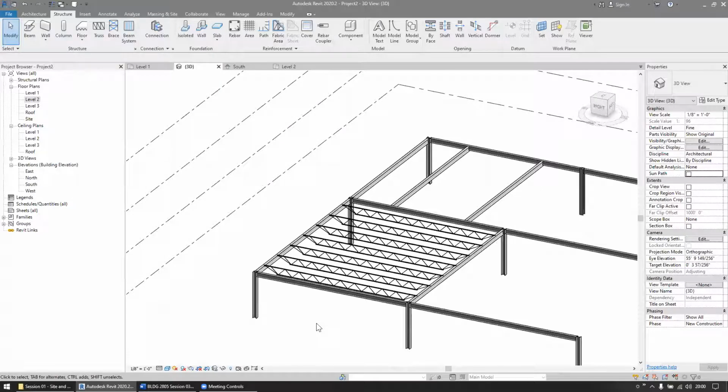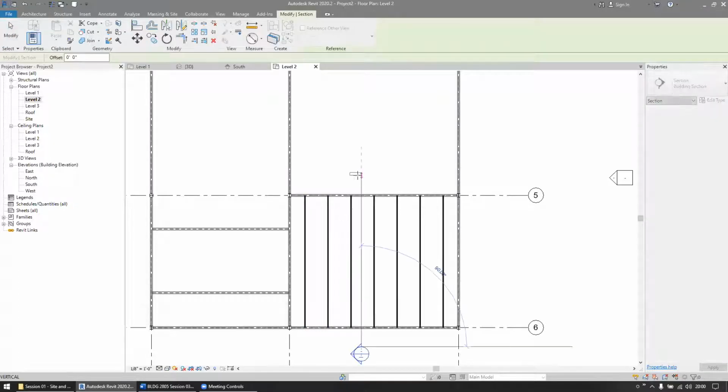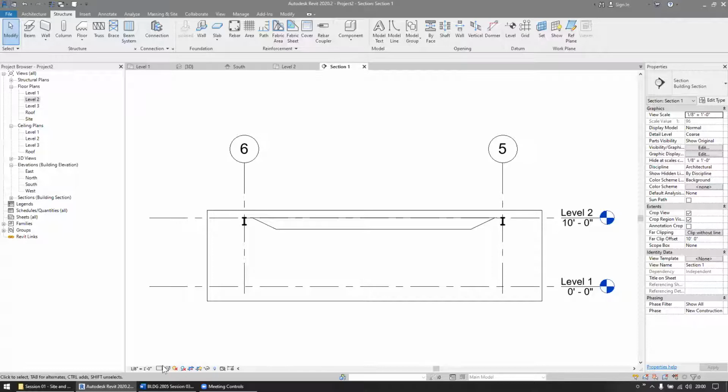And this is pretty cool. Now we're going to talk a little bit here about steel construction and just how you need to arrange all of the steel structure on your project. Now this may not pertain so much to wood frame, but with steel there's certainly a definite order with which everything needs to be arranged. Let's talk about that. So I'm just going to cut a section here. So I got a section that's going to be cutting through our steel structure. And I'm going to set my level of detail to fine here so I can really see the geometry.